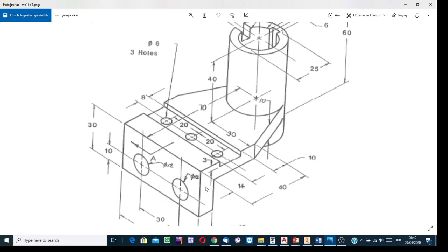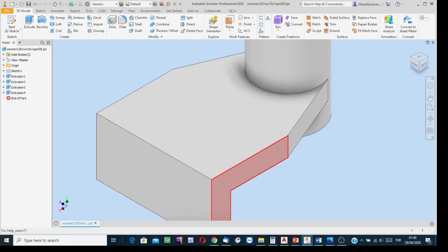Take a sketch right on the most front surface, and then draw what? Draw the edges of the selected surfaces. The edge of this profile surface, while the object is observed in this direction, is seen as a vertical line. The edge of the other surface is this vertical line, and the edge of the horizontal surface is that vertical line. Since the surfaces are perpendicular, for having their edges in sketch mode, I can create a rectangle. This is my plan. Left click to indicate the surface, right click the mouse, and then take a sketch right.